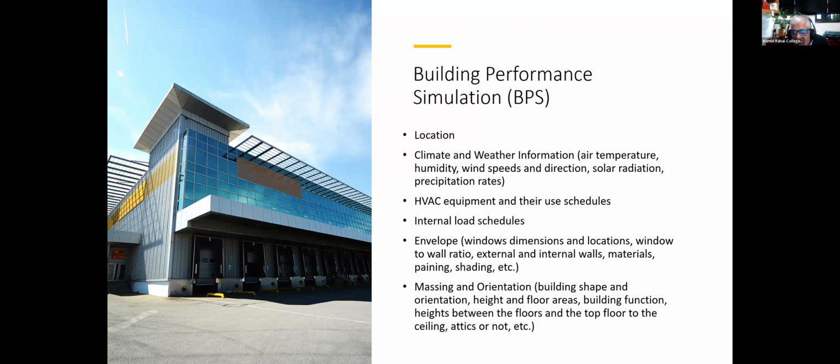Internal load schedule. So, for example, for our buildings, at 8 o'clock the load is different than at 11 o'clock a.m. And also in the afternoon, the load is different. So depending on the load, you can control the HVAC system to meet your load requirements. This way, you don't have a fixed amount of air coming in and going out. You meet the load according to the internal operation or internal occupancy, and based on that, you can also save energy.